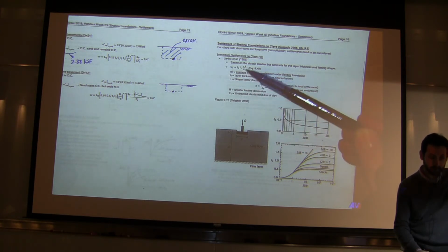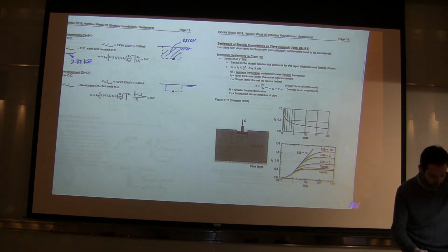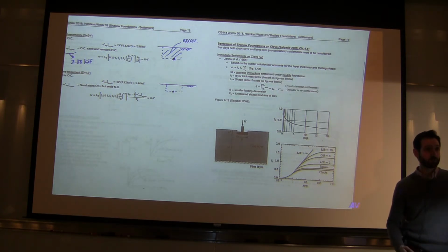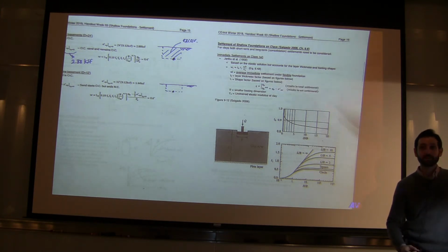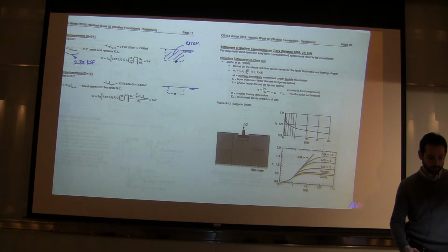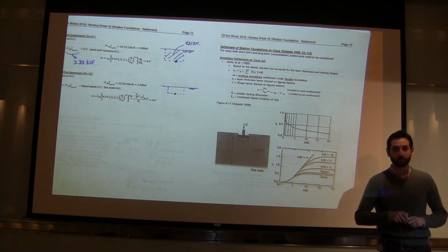And then we also have to find q. That's easy. The structural engineers already give that to us. It's either the factored load or the unfactored load. B is the dimension of the footing. Again, we already have that. And in the denominator is E sub u, the undrained shear modulus or undrained elastic modulus of soil.